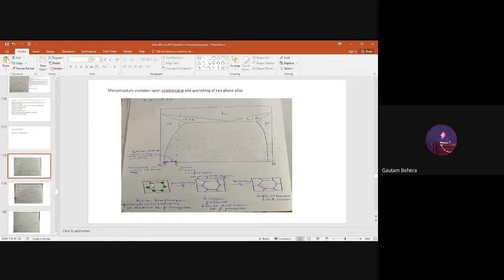You might end up with bigger precipitates, non-uniform distribution of precipitates, and precipitates of poor properties after casting. So you need to do what? You need to again heat at this temperature, again quench it, then you do aging after that. What will happen? Uniformly precipitate will form everywhere, maybe, right? And that may be of the required size which you want.